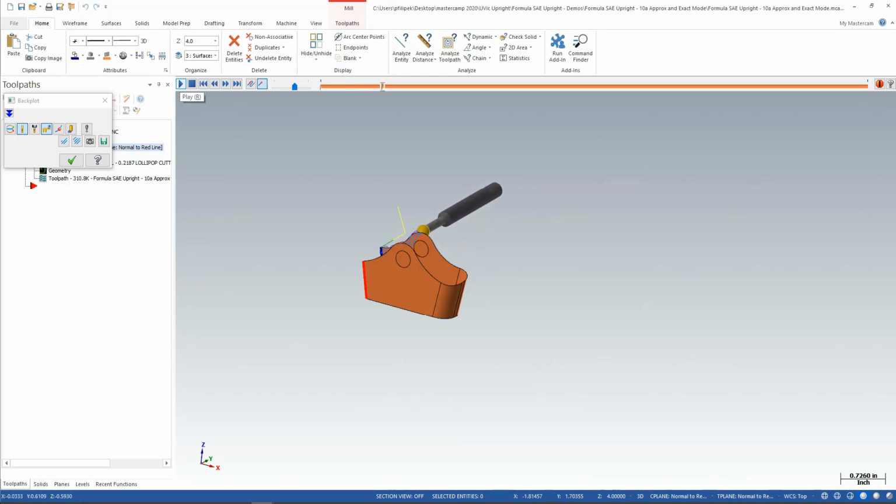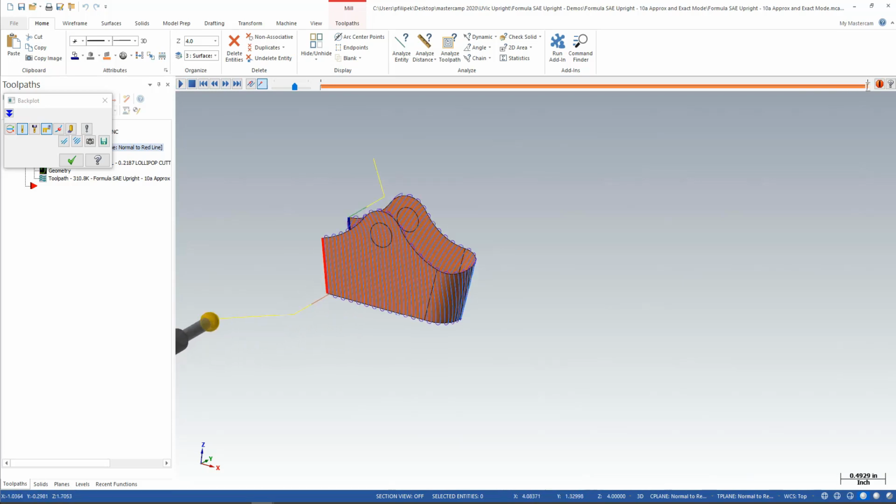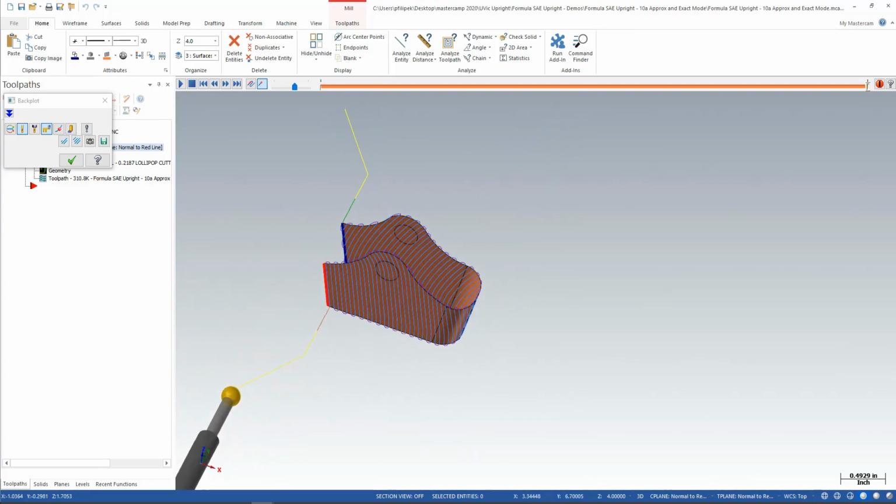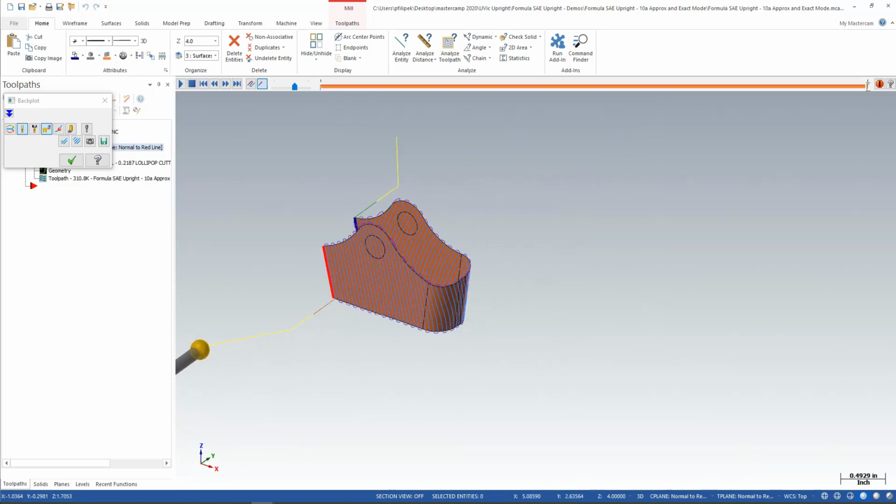Now watch that cut. Just by going to exact mode, that has essentially fixed my whole tool path of where I was seeing issues before. So now that tool path can work its way around there correctly, still going parallel to the curve that I picked, but now just going to an exact mode. So it's a lot cleaner tool path. I mean, that's quite a change just by one switch in 2021 to go to exact mode. It's kind of huge how that fixed it.